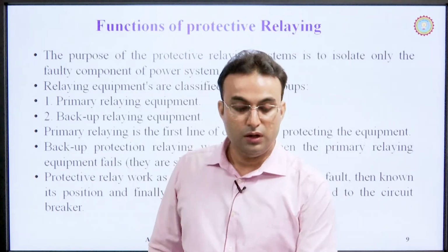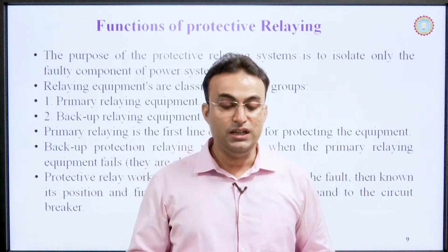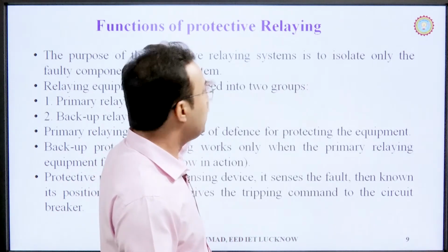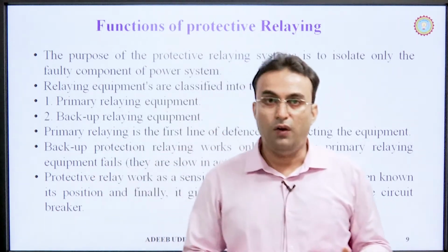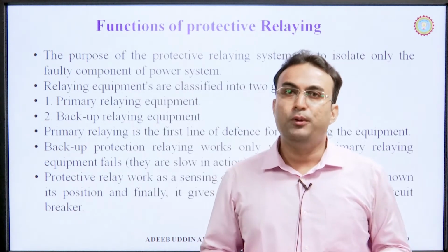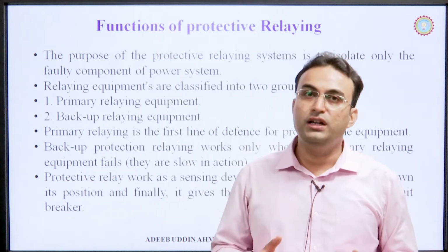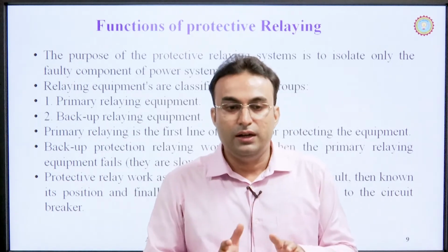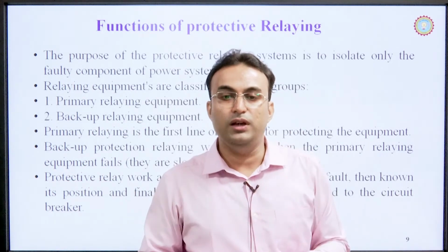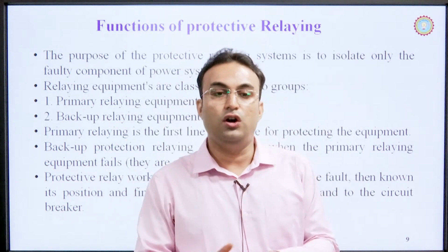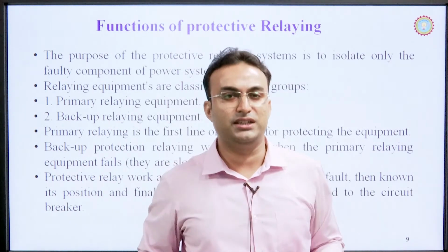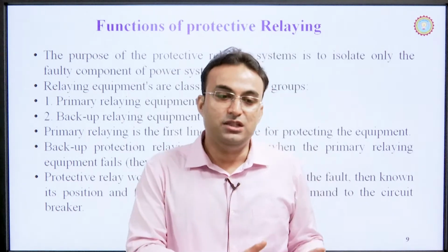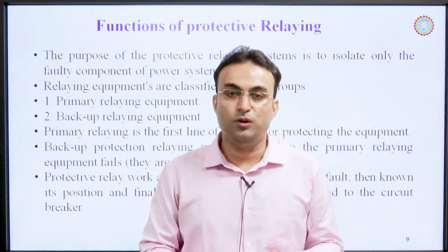Now, our next topic that we will discuss is the function of protective relays. So, basically what are the functions of protective relays? These are the responsibilities, or you can say the fundamental duties, of the protective relays. The purpose of the protective relay system is to isolate only the faulty component of the power system. The fundamental duty of the relay or relaying scheme is to detach or separate the faulty section from the healthy section. That line is very important in the power system. You have heard many times about detachment or isolation of the healthy section from the faulty section.